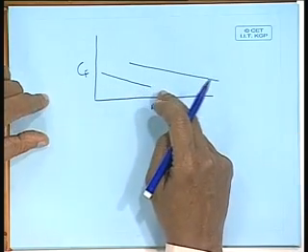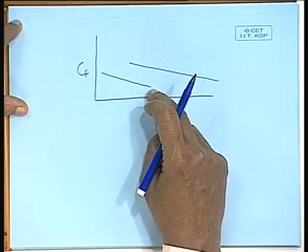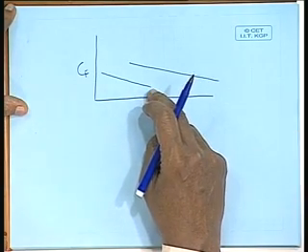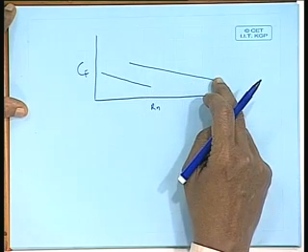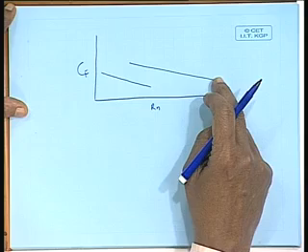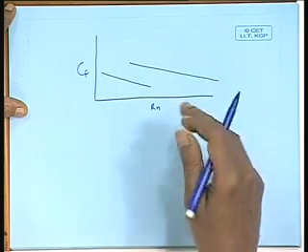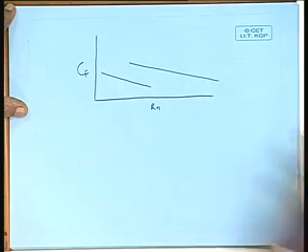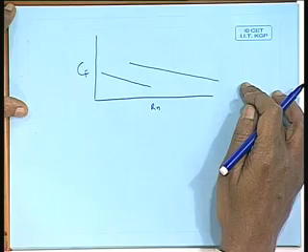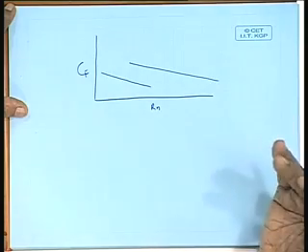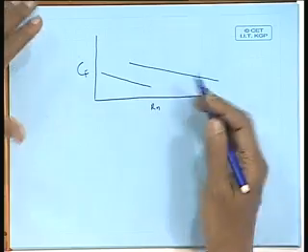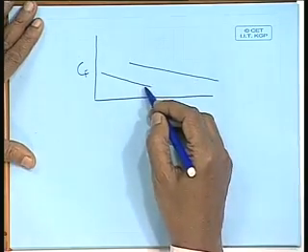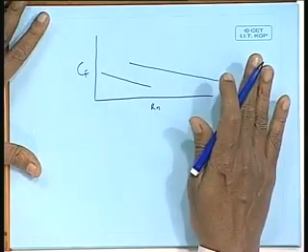If you remember, we defined a Blasius laminar flow line and a Prandtl von Karman turbulence line, which was later advanced to the so called ITTC line, which is slightly higher than the Prandtl von Karman line. But basically whatever formulation you take, there will be a formulation separate for laminar flow.